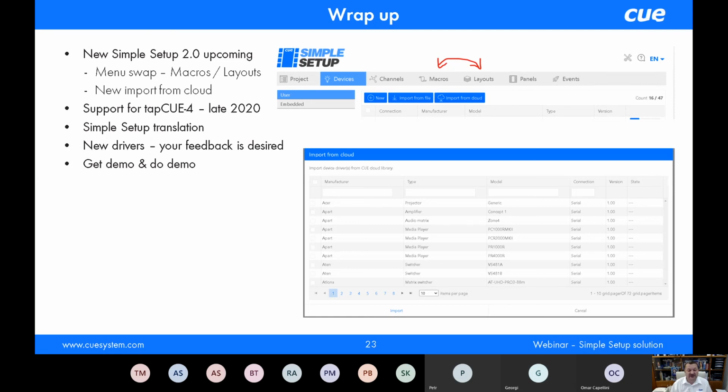Okay, I got one more question. Do you need to set an address on Keypad Q55? It is necessary to differentiate the keypads, so that each keypad will have a different ID. The ID is used for differentiation between multiple keypads if you have an environment of multiple keypads.